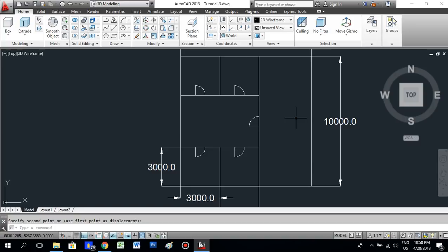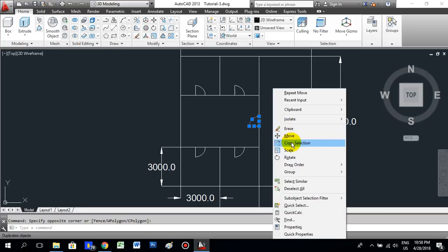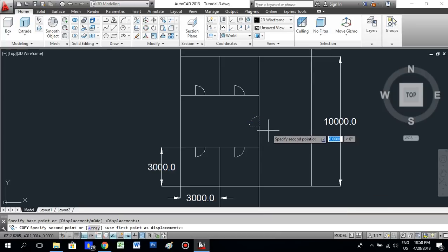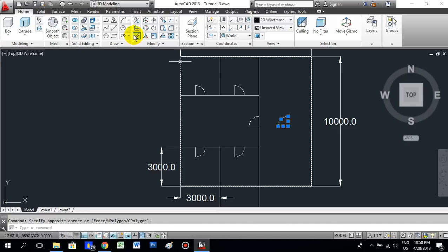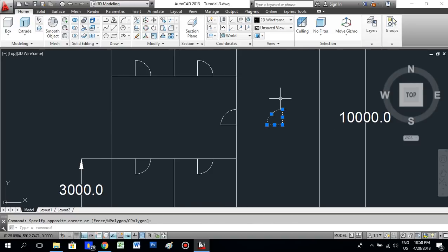that means front hall. So for this hall we are going to make two doors, a double door. Okay, so for that we are going to use the same door, copy that door, move it, click here somewhere, press enter, finish the copy command. And now we are going to use the same mirror option to make two doors.